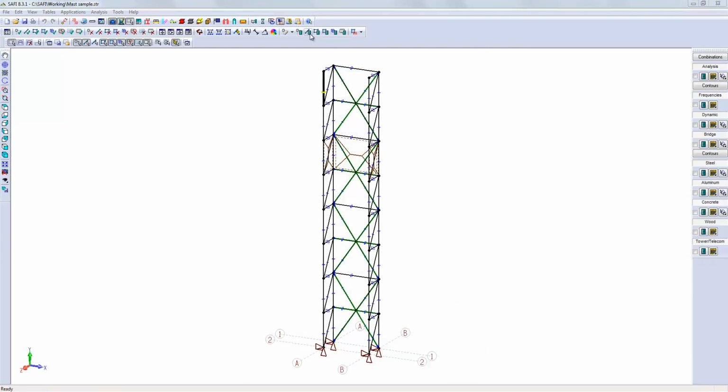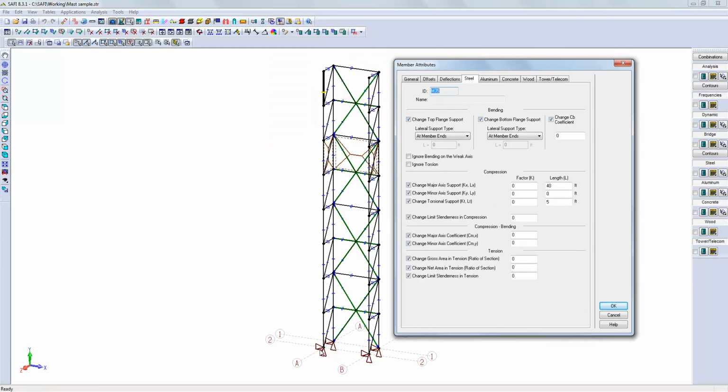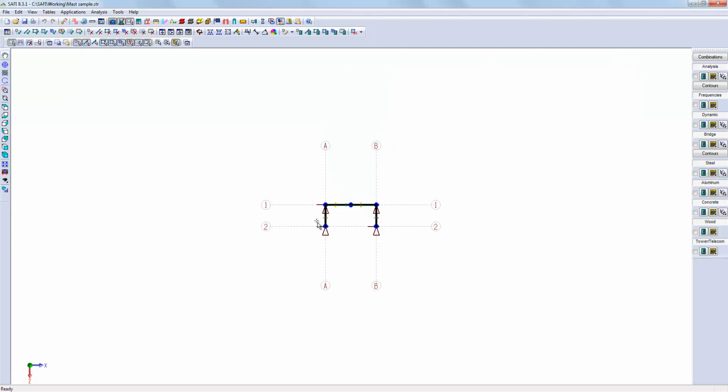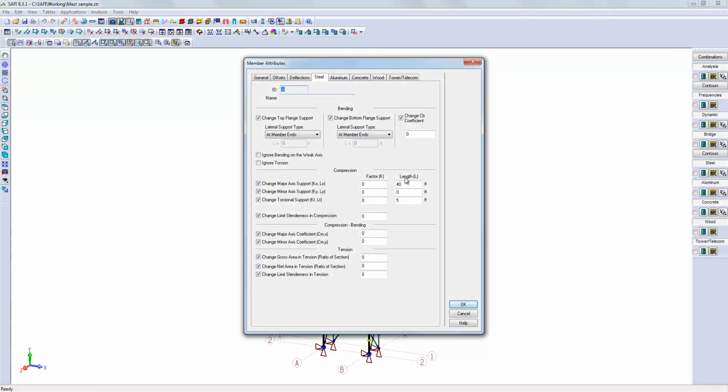In this example, if we look at the front members, because there is no lateral support from top to bottom, the software measures the buckling length as the total height of the structure. This would be too conservative because the horizontal members provide some sort of lateral support. Because those supports are not fully efficient, we will assume the buckling length as twice the height of the member, which would be 10 feet. Every designer should do his own assumptions regarding the design of his structure.